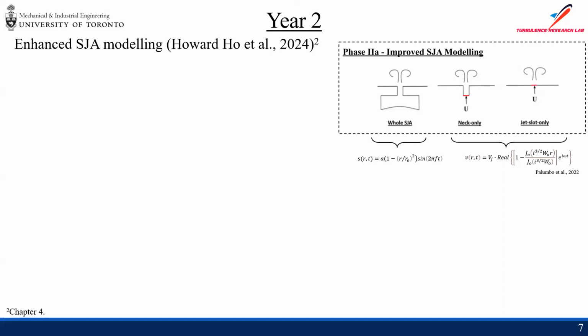I have to solve the new displacement of the mesh in the XYZ direction. The displacement has to be diffused inward, and I also have to update the pressure solver, prior to calculating the velocity field. It's a very expensive, costly method.